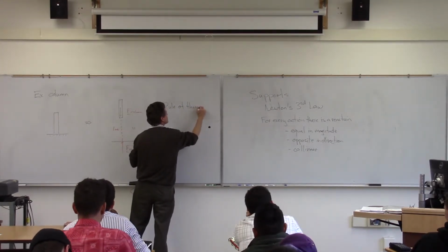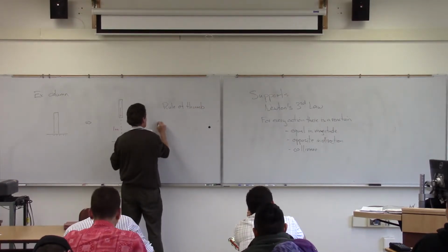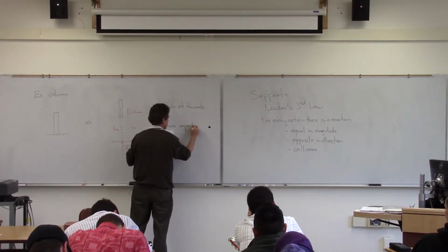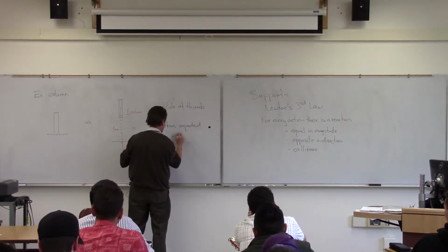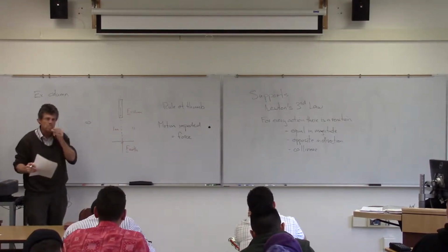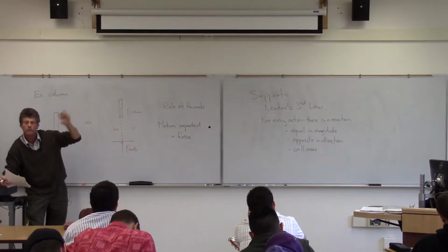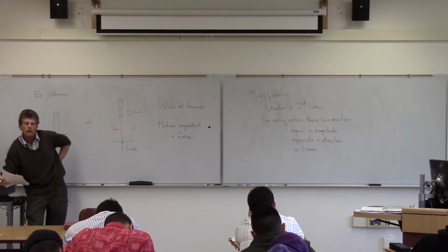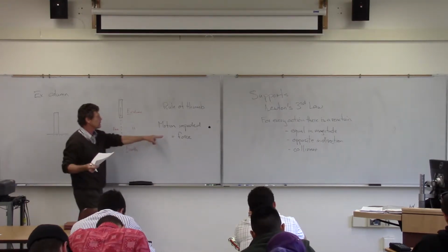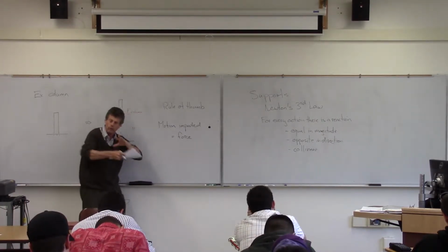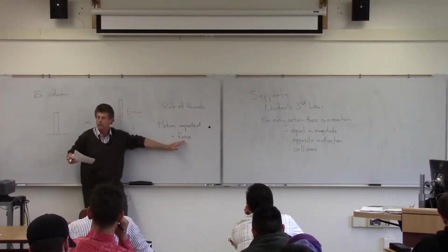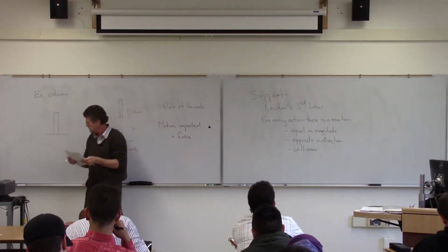Because we'll talk about this when we look at these examples. The rule of thumb: if we think about our free body diagram, if there's some motion that's impeded by pulling it away from a support, say I've got a support here, and that support is saying I'm not going to allow you to go into the ground, then when we replace that support, when we pull that isolated mechanical system away from that support, what we're going to do is substitute a force. Now, we'll talk about that when we start looking at some of these examples.